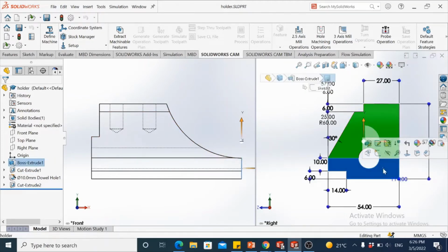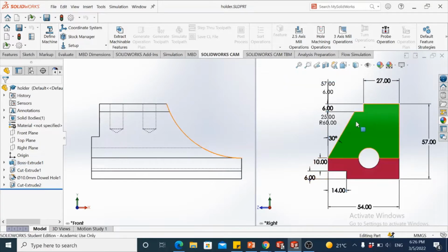When I pick up this, I find that it gets highlighted onto the vertical edge coming on the right face of the front view. So the whole shape as shown in here appears as an edge in the front view. So this is how we try to visualize the various features, by looking at the surfaces and then their corresponding sketches in the other views. So we have 2 of these already identified from the side view.